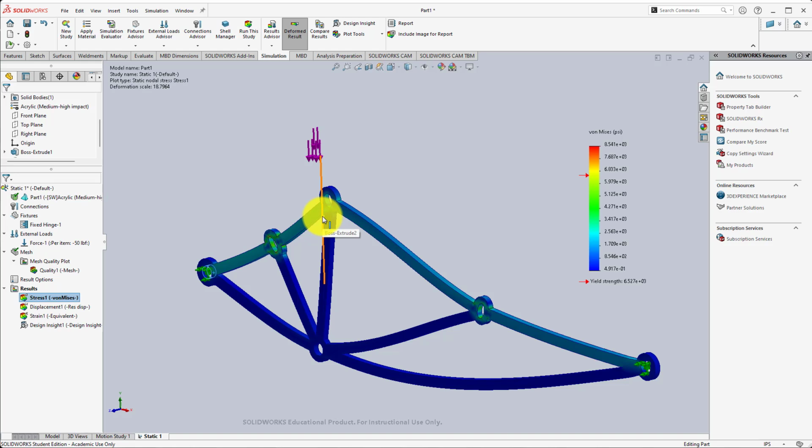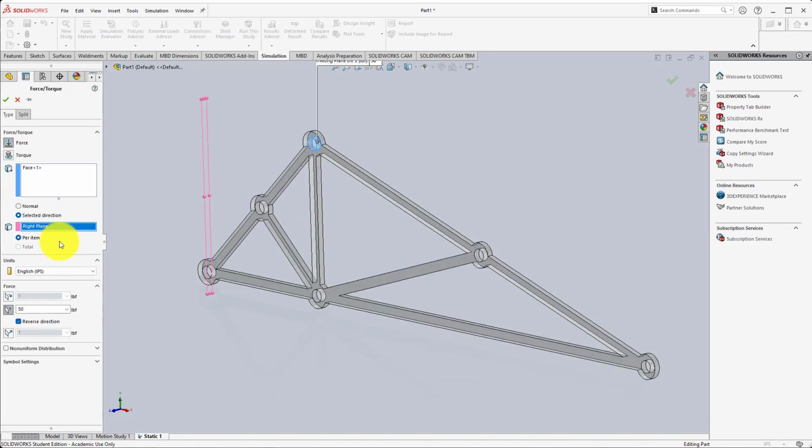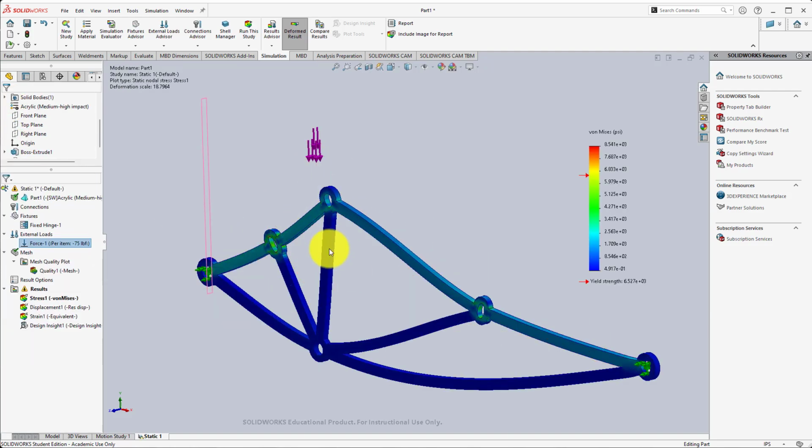And the way I drew it, I can go back in there real easy and change those in the sketch, modify that, and come back in here and see this. Now, what kind of load do I want to see? Let's say that eventually I get it where the yield is not showing and the frame is a lot stronger. Well, you can put a bigger load on here. I could edit this definition. What if I wanted to put 75 pounds on here? Now, some of you are going to have frames that can hold 100, 150 pounds per side, and that's going to be pretty impressive. I changed that, and it puts a little notice here that I need to update the results, so I'm going to rerun this.